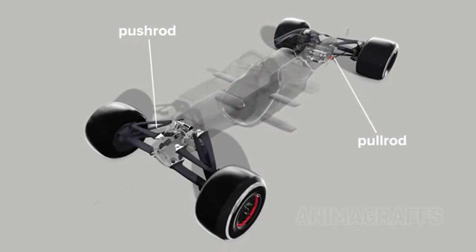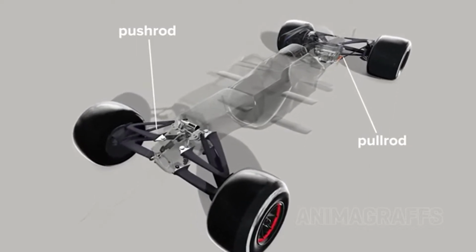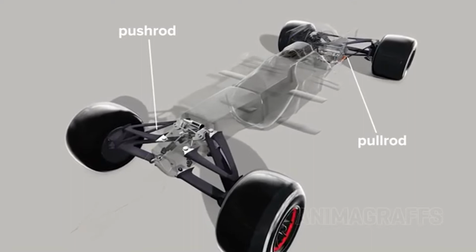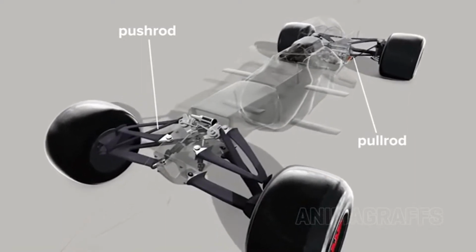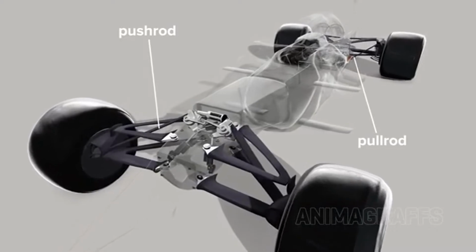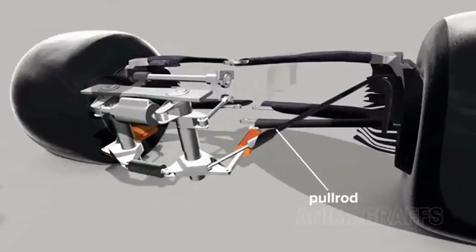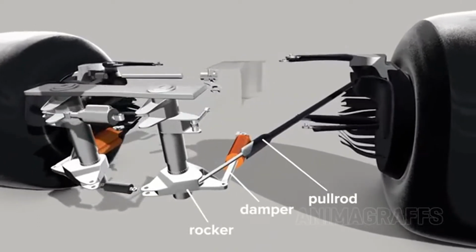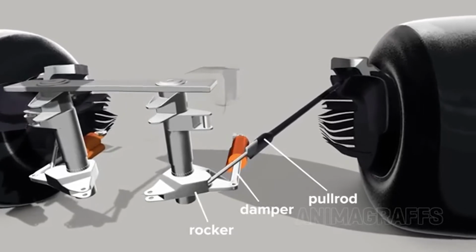Our model has push rods in the front and pull rods in the back, which simplified just indicates how the system is mounted: to push or pull connected suspension parts. If parts can be mounted down low for a lower center of gravity, all the better. The pull rod connects to a rocker and damper, which we call shock absorbers in normal cars.